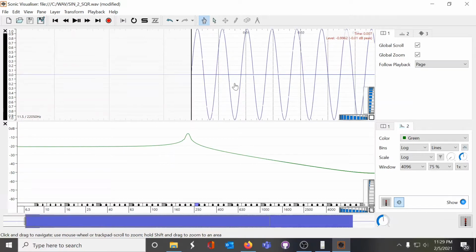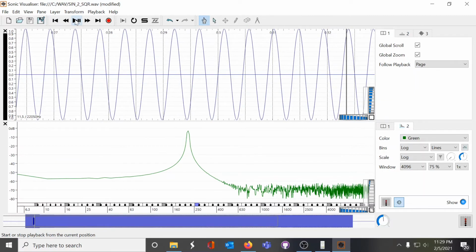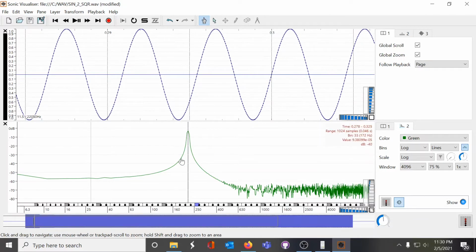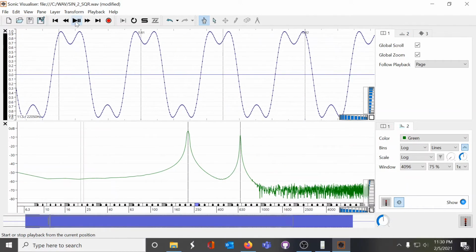It started out easy enough. As with our previous example, it looks like a sinusoid in the time domain. It looks relatively clean with no distortion. In the frequency domain, we can see that it's clean. There is no distortion. There are no harmonics here at all. It's a sine wave. Here, it changes. We get this second peak of energy. So our fundamental was 220 hertz, but now we have this second frequency at the third harmonic.